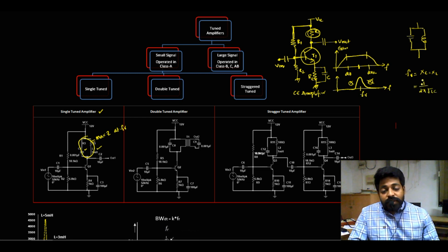At that frequency the tank circuit is under resonance. The capacitor takes the entire energy from the inductor, and the inductor takes the entire energy from the capacitor. So energy is transferred between these two components, and the external current drawn from VCC is around 0. When the current is 0, the entire circuit behaves like an open circuit, offering maximum impedance.